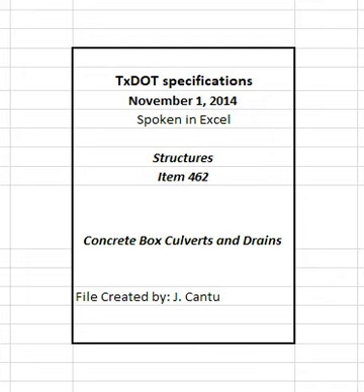Where inlets, head walls, wing walls, catch basins, manholes, junction chambers, or other structures are included in lines of culverts or drains, the length of box section tying into the structure wall will be included for measurement, but no other portion of the structure length or width will be included. The measured length of multiple barrel structures will be the sum of the lengths of the barrels. This is a plan's quantity measurement item. The quantity to be paid is the quantity shown in the proposal unless modified by Article 9.2, Plan's Quantity Measurement. Additional measurements or calculations will be made if adjustments of quantities are required.